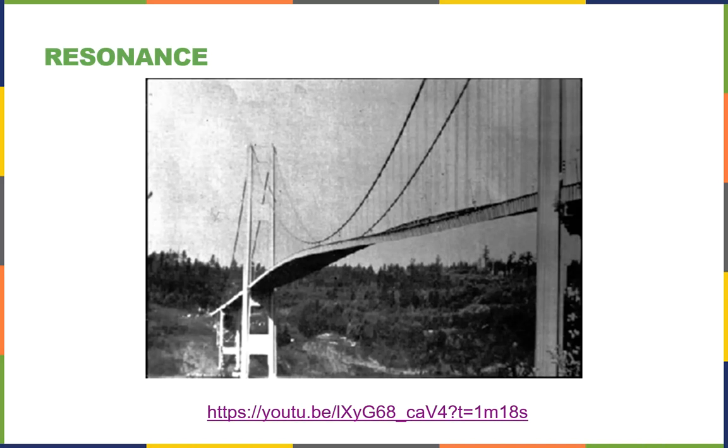And that's what happened with that Tacoma Narrows Bridge. The vertical wires were essentially being plucked by the wind. Wind blowing on those wires goes around and it makes what's called Kármán vortices. Little eddies of air go flying off of them. And each time an eddy flies off, it plucks the string one way. And they alternate the direction, so the wind is just plucking the string back and forth, and the frequency of its plucking is proportional to the wind speed. And if that frequency is the same frequency at which the string would naturally vibrate, then the amplitude gets bigger and bigger.